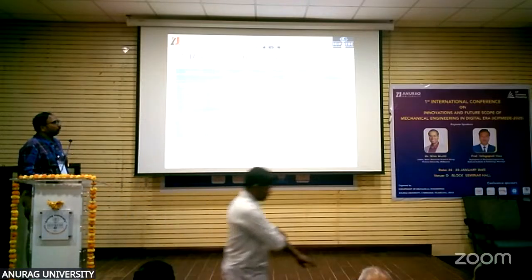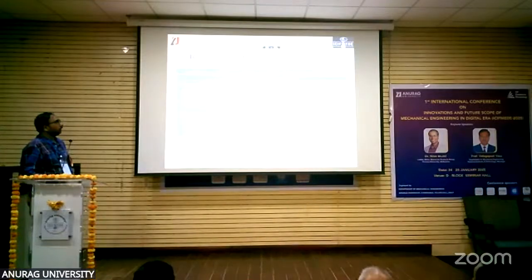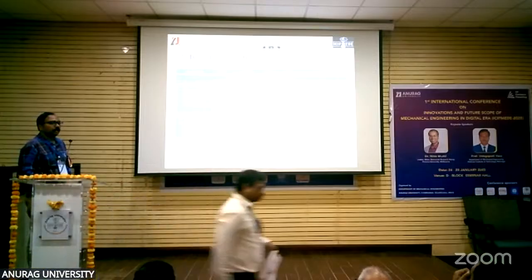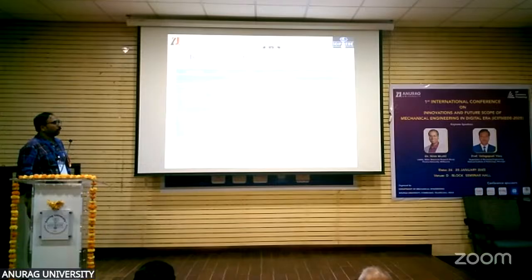Further, the ANOVA has been determined. In this ANOVA, the maximum contribution for thrust force is from the feed rate, around 85.7%. Whereas for the delamination factor, the carbon nanotube content contributes more, with 63.7%. Now using the additive law, I have predicted the values for the 3 parameters.